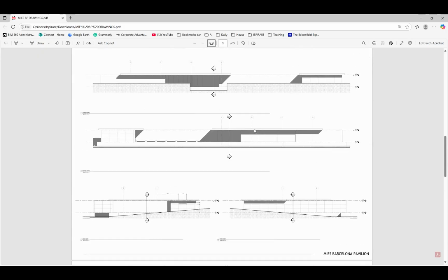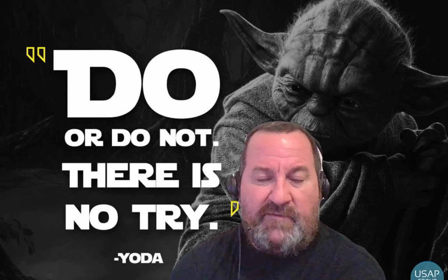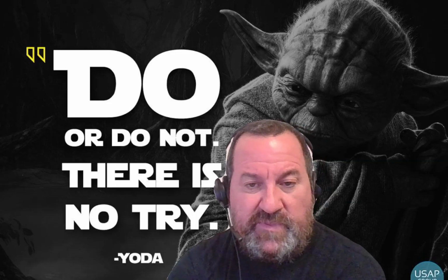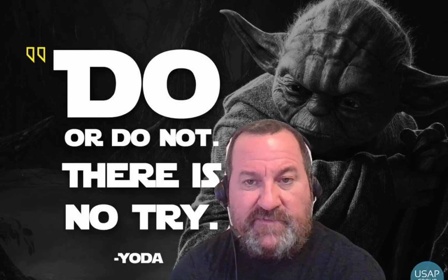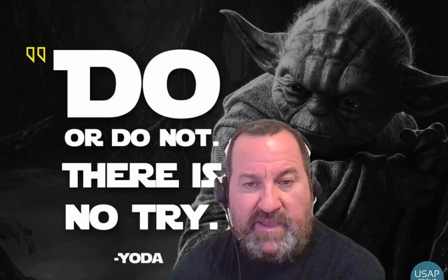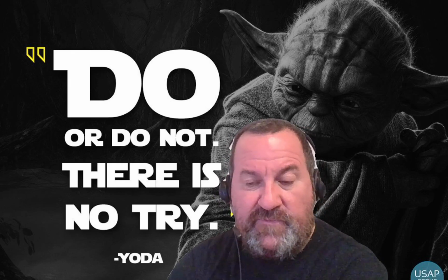All right, so what we've learned this evening anyway is how to manipulate views within Revit, how to add those views to sheets, and how to create PDFs. That's the extent of what I was hoping to achieve with this video.